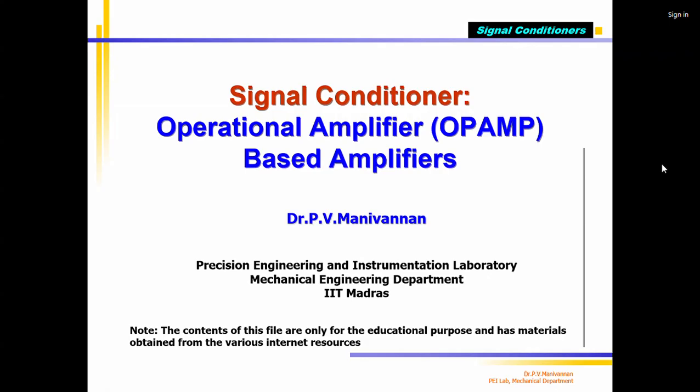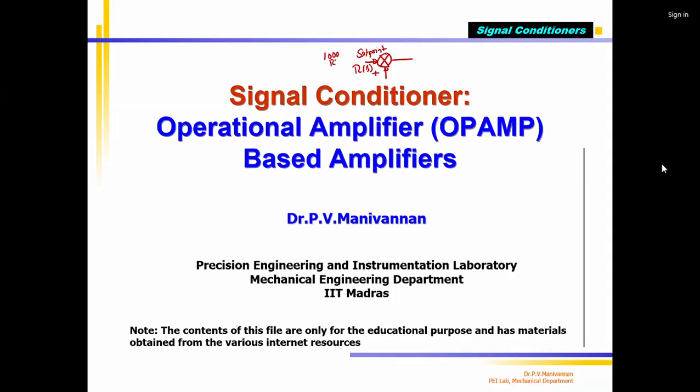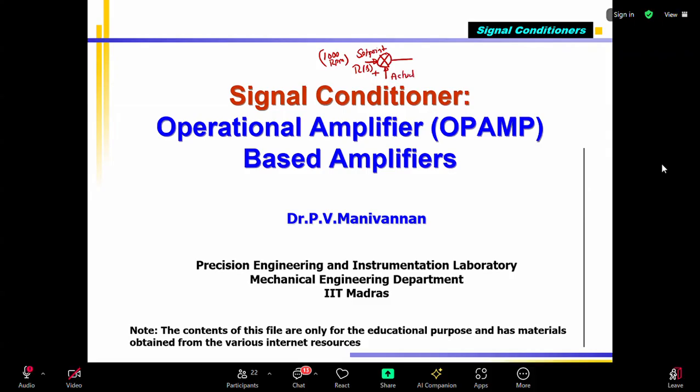But please know that the sensor signal, we saw in the functional block diagram of a mechatronic system. I will draw a miniature version. I have my set point. For example, I want to control engine speed. The set point we call RS, given to the plus input, and the other input is the actual engine speed. Set point I say 1000 RPM, the engine speed I want to maintain. The actual current engine speed we are measuring using a sensor, the engine speed sensor.